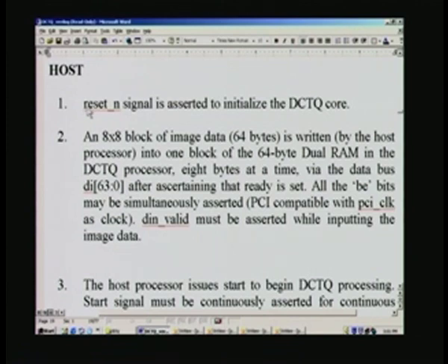If you do not want latency, do not assert reset except right at the beginning when the system is switched on, or deliberately when the whole JPEG or MPEG is initiated. At that point only you need to reset, and thereafter do not reset, and probably after processing one frame, if you feel like it, you can initialize once again, if the need arises. Otherwise you can use the hold signal, and dispense with the latency, and thereby you will speed up the processing considerably.